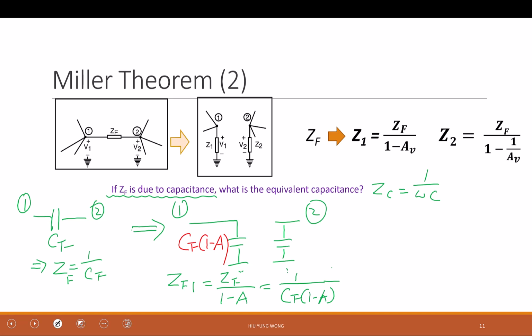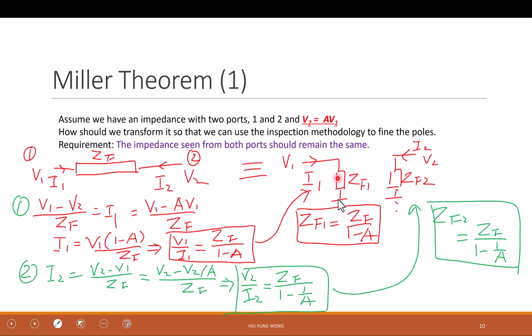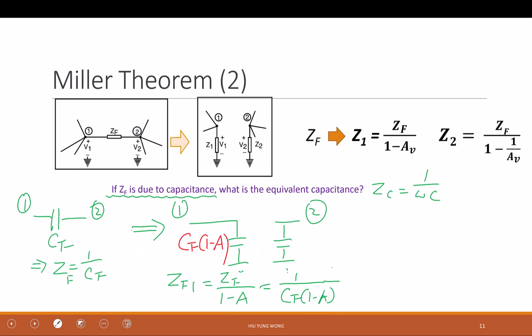For inductor, then it's the same. For resistor, it is the same. But for capacitor, because of this reciprocal relationship, right? You assume this is larger than 1. You will feel that I need to reduce the impedance by certain value. I reduce it, right? But for capacitor, you need to increase it so that its impedance can be reduced. Larger capacitor, smaller impedance. Make sense? Right? So similarly, now someone talking about negative, I will show you later. Yeah, you feel that that's negative, right? But we won't.